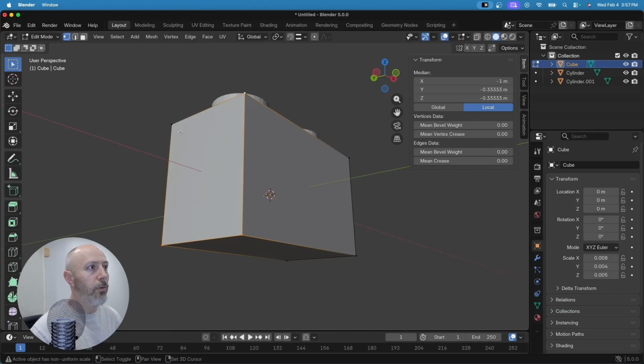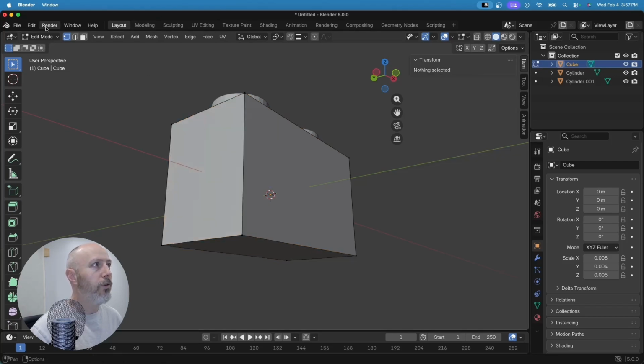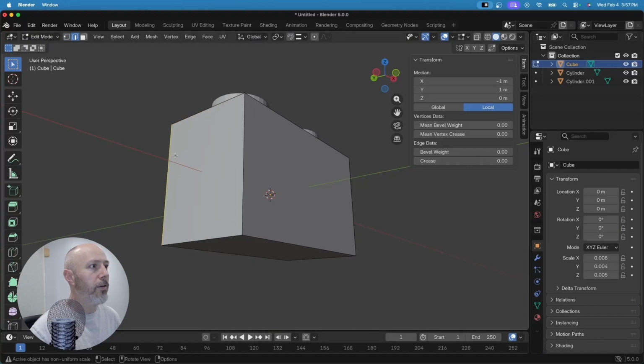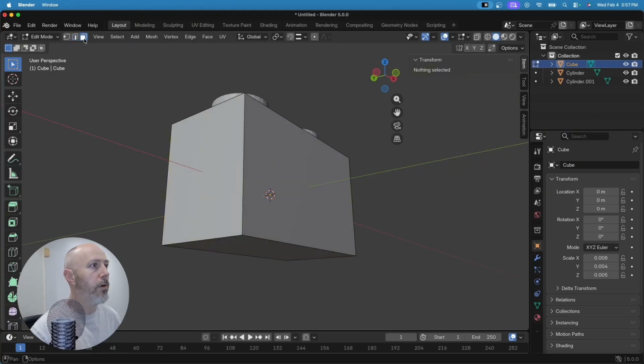And then the most comprehensive of the constituent parts is a face. So we have edges, and we have faces, and we have vertices. And wouldn't you know it, there are 3 different selection modes up here in the upper left corner of the interface when I'm in edit mode that let me select vertices or select edges or select faces.